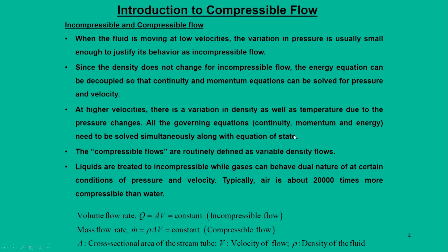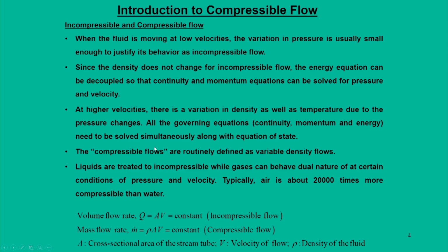There the governing equations, continuity, momentum and energy equation need to be solved simultaneously, which means that in an incompressible flow domain, if we solve the mass and momentum equations, then we need not couple the energy equation, and the energy equation can be solved independently. But in a compressible flow domain, all three equations have to be solved simultaneously along with the equation of state, and it is mainly applicable for gases.